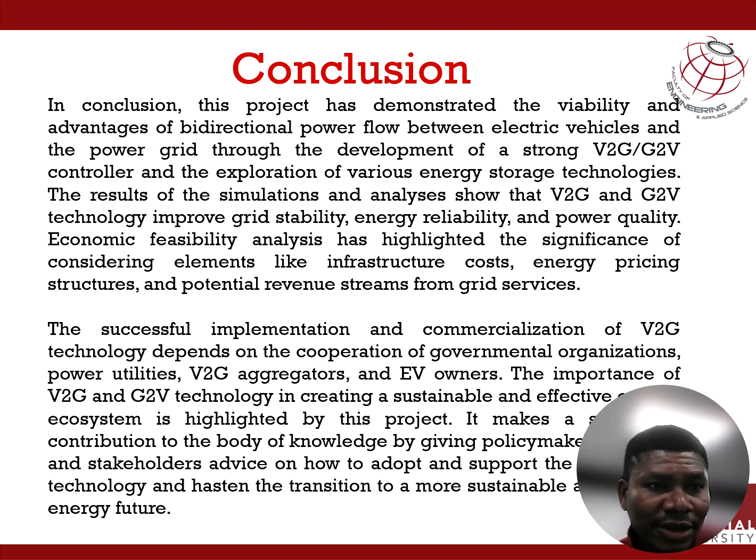Now, conclusion. In conclusion, this project has demonstrated the viability and the advantages of bidirectional power flow between electric vehicle and the power grid through the development of a strong V2G and G2V controller and the exploration of various energy storage technologies. The results of the simulations and the analysis show that V2G and the G2V technology improve grid stability, energy reliability, and the power quality.